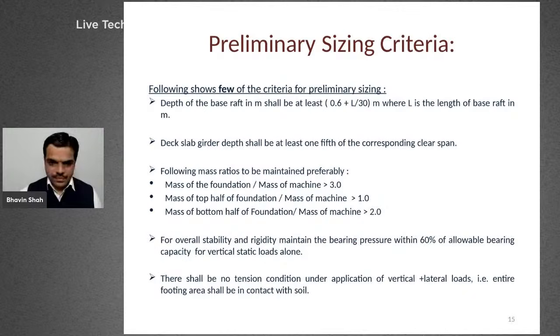If we talk about the preliminary sizing criteria, here I have summarized a few of them. Why are preliminary sizing criteria very important for this kind of foundation? Because a lot of trial and error will be involved if we have not picked an appropriate foundation size from the beginning.